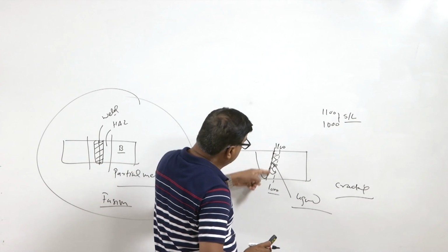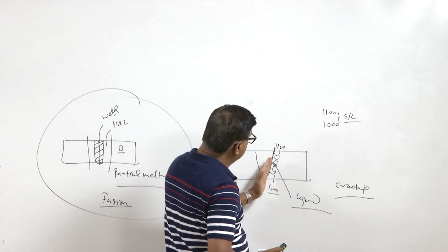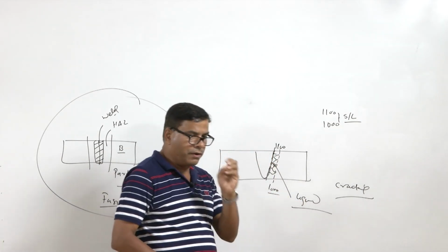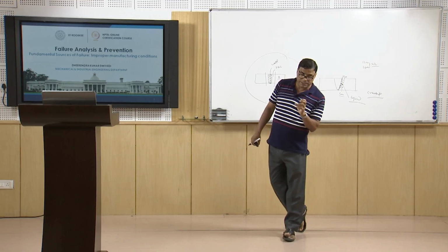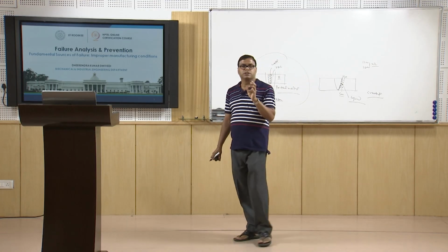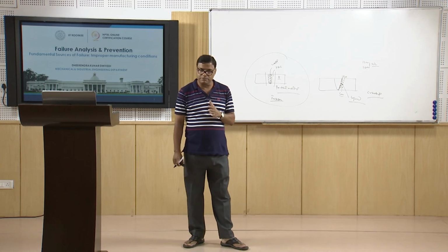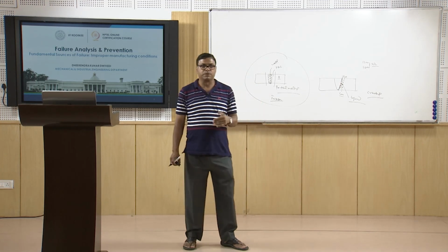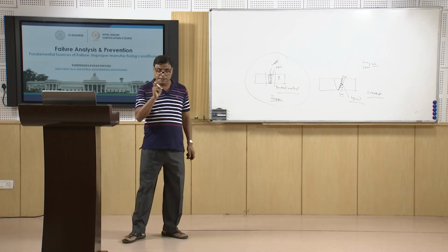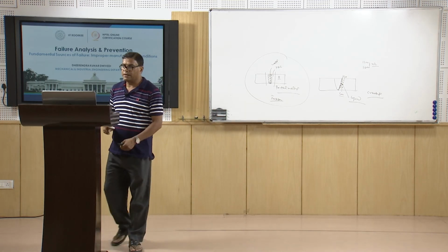So the fusion boundary is this one, and the zones next to the fusion boundary, where both solid and liquid phases are present, in the presence of tensile residual stresses promote the cracking, which is called liquefaction cracking.